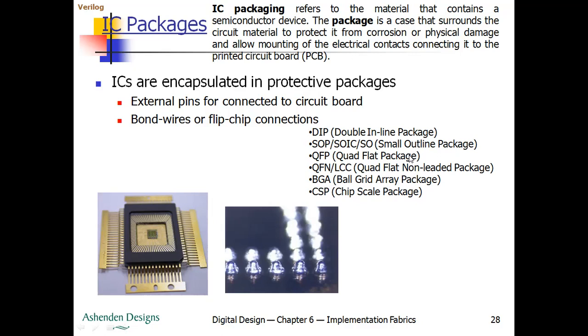So the choice of a particular package will depend upon the number of connections required. You can go for either DIP or SOP or QFP and so on. That depends upon the number of connections required and the environment of operation of the particular IC. So based upon the environment of operation as well as the number of pins, you can go for the appropriate choice of the IC package.